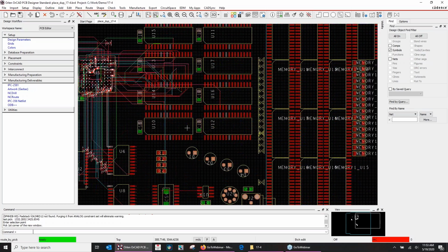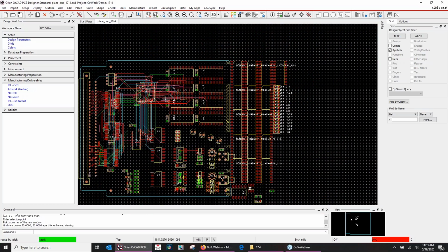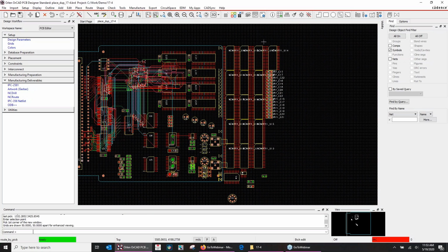A good example of what if is the engineer took all the time to put all these memory chips on here. All right, I've got 8 here. I've got another bank of 8, and I've got another bank of 8. I can put the memory chips on the back side and put a bank right underneath here, but I'm going to maybe be hard pressed to get the other 8 on here and the termination that I needed for those. Now, that was a lot of work on the schematic part. So if that engineer would have come to me and said, what if I added 2 more full banks of memory? Can you fit them on the card?